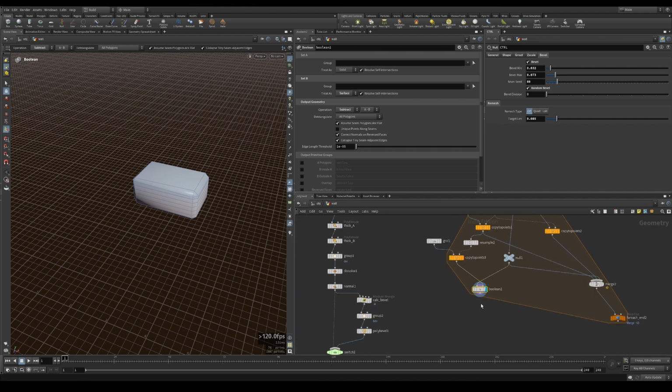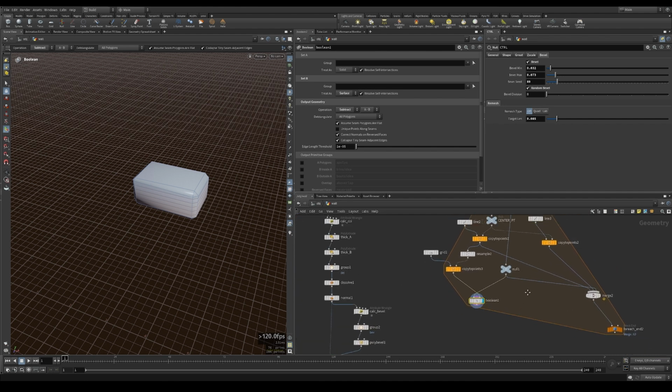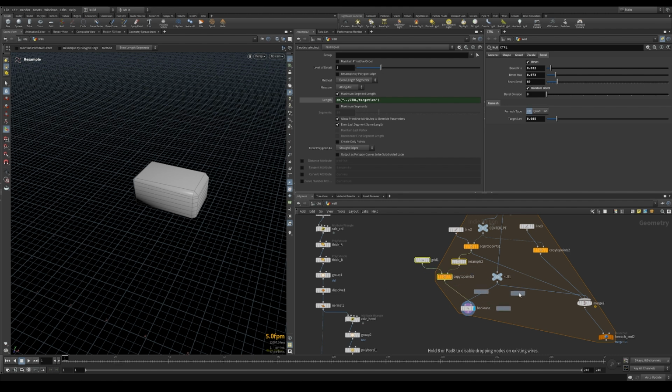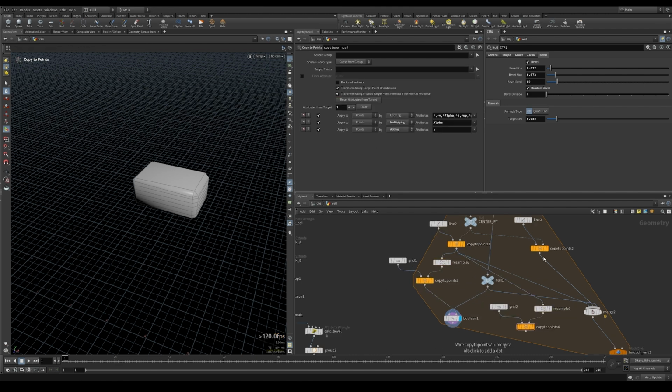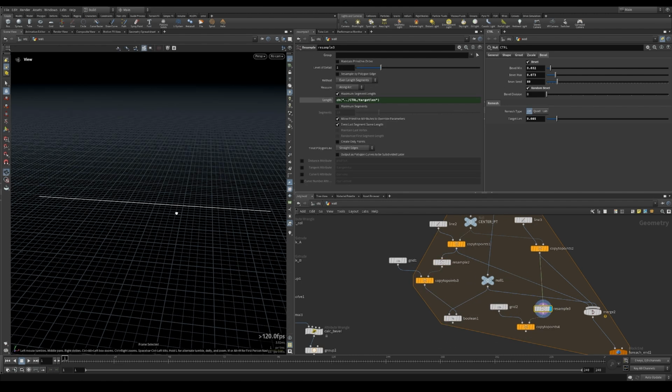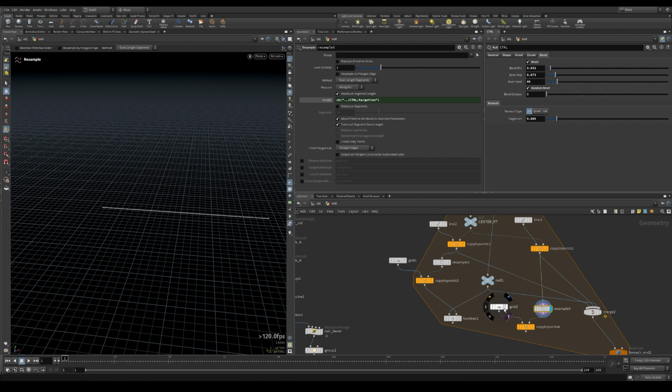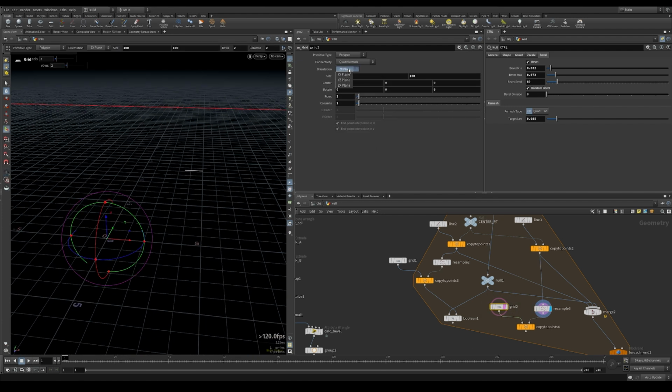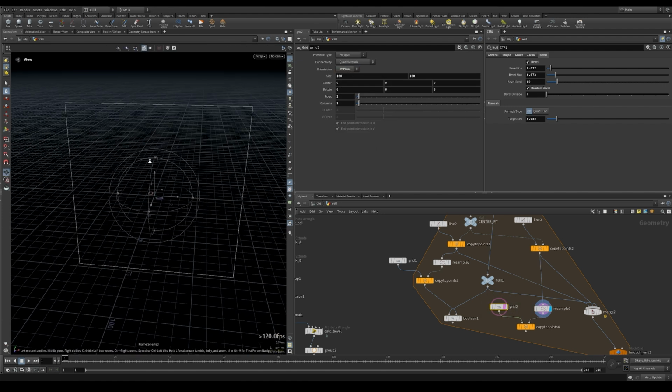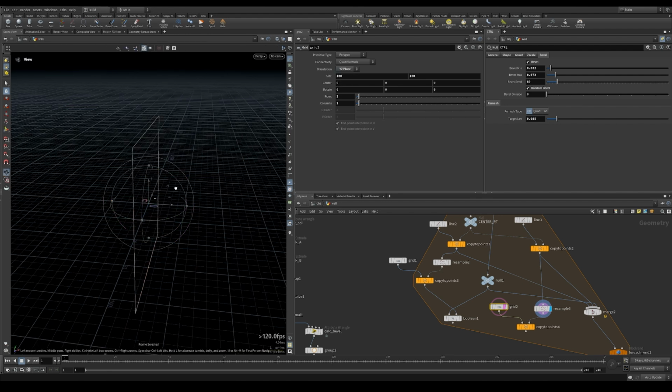And we want to do a second time for the other set of grid. So copy these 3 nodes. This will go to the other lines. So this is the horizontal line, and we also need to change the orientation here. Let's see, YZ plane.